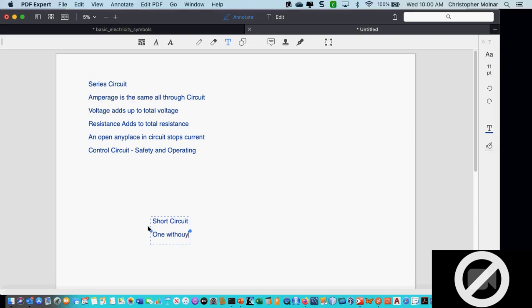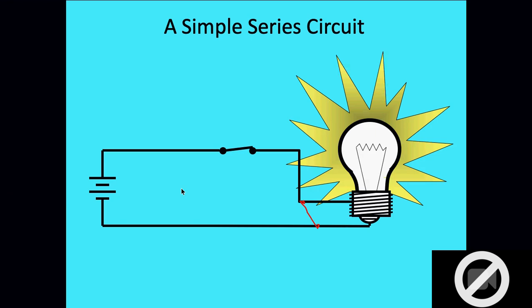I have a question. When you have a fuse that blows, why would putting in a higher fuse, like say you have a 30 that's blown, you put a 40 in, make it different? Sometimes a fuse will blow because, for example, somebody has added an extra motor or something to the circuit, or added extra computer equipment to an area. That's not necessarily a short circuit. That's why you do have to go find out and look. In HVAC, never do that.